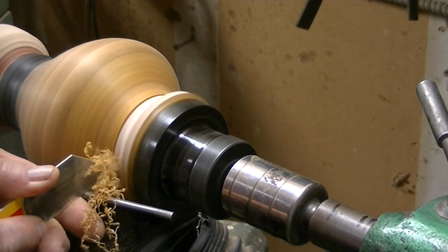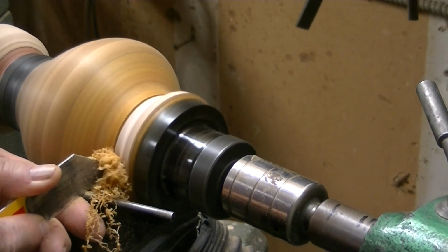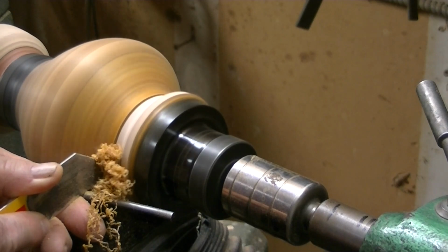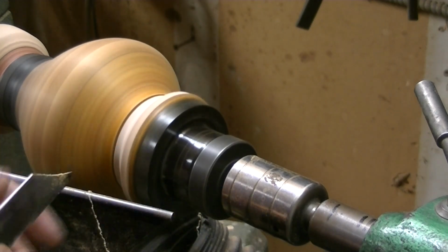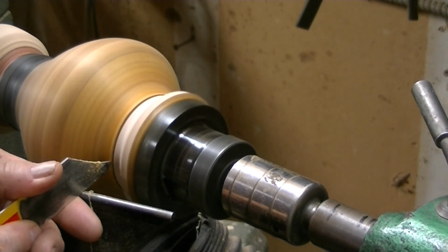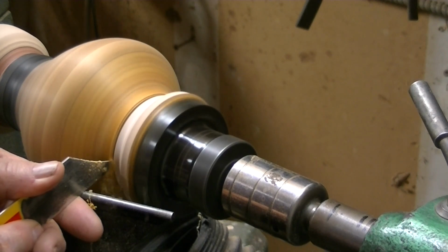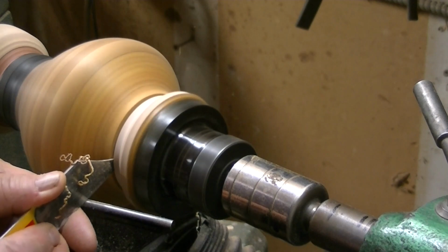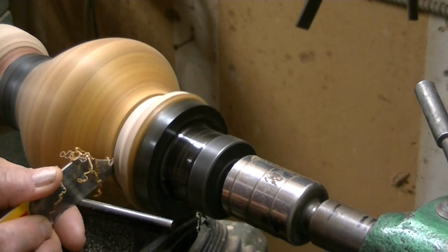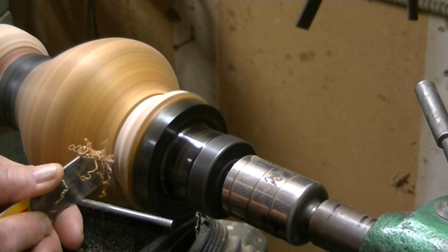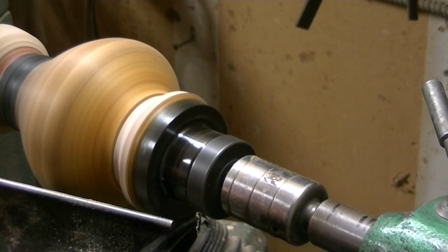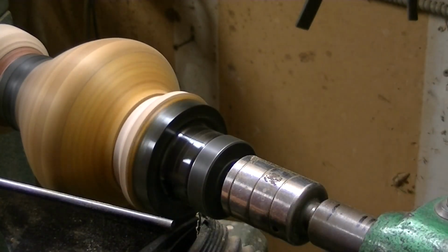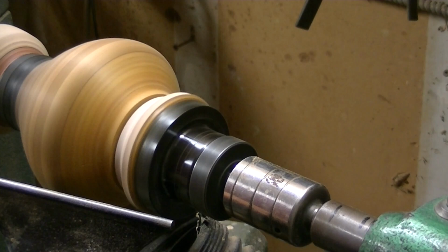So I'm using a thin parting tool, specifically one I've made myself, that takes away very little wood. But I still do overlapping cuts. One cut goes in, the next cut goes over about a half of the tool width, so that I never have an opportunity for the tool to get bound into the joint and jerked out of my hand. And after a few cuts, we eventually part off the glue block.